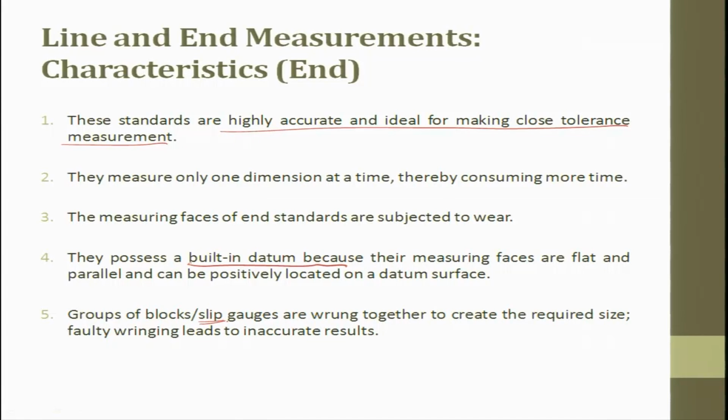So, what is slip gauge at this point of time? Suppose we have a block. You have several blocks of flat plates which are attached. You make sure all these flat plates are attached to each other without any gap. So, how do you make sure? That is the wringing operation we do. So, they do not have a gap in between, and they also do not have any inaccuracies on the flat surfaces. This is for end to end measurement.